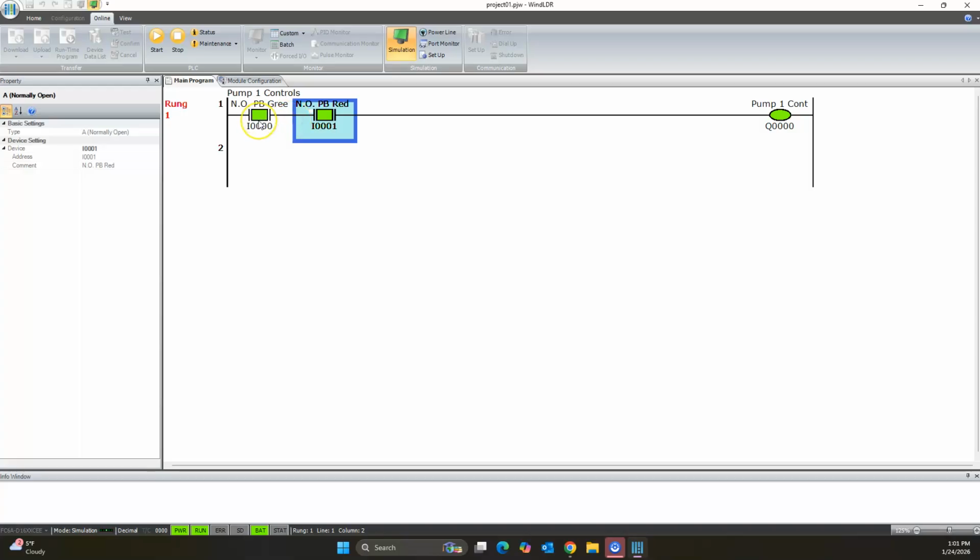So these are normally open, momentary push buttons. So this is where I say the simulation mode can trick you. Because what do I have to do in the real world to maintain that 24 volts that we're sending to this input and this input? Well, I would have to physically hold down those buttons this whole time. As soon as my finger lets go of one of these buttons, this resets back to low, false, or 0. I lose 24 volts to input number 1 if I let go of the red push button.